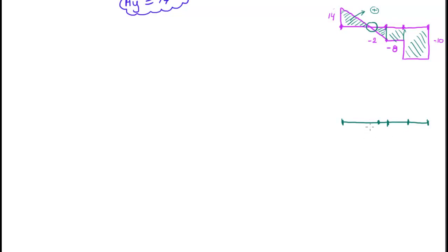Okay, so as I promised you, if we calculate the areas under the shear diagram, we should get some values here. The value at this point is the value of the area under the shear diagram for the whole shear diagram before that point. What about at this point, which corresponds to this one right here?